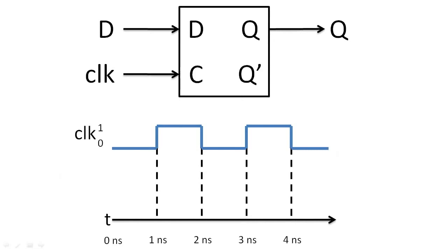When we design sequential circuits, we want to synchronize the times when all state storage components store new data. We synchronize these components with a signal called the clock that oscillates between 0 and 1. To help synchronize our components, we can add a clock input to our latch that acts as a gatekeeper that allows the latch to change its value only when the clock's value is 1.